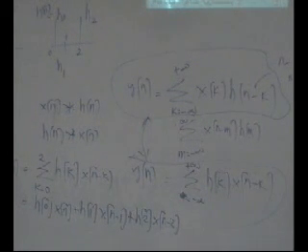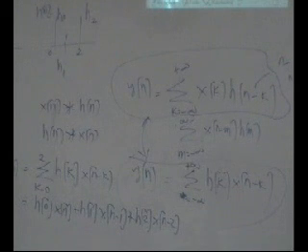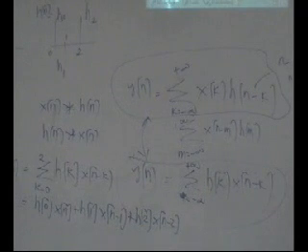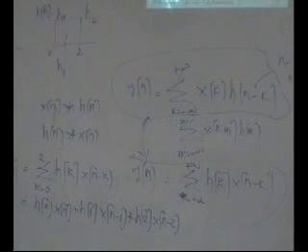So there are two ways of looking at a system, both analytically equivalent, but two different implementations. And you will keep learning about more and more implementations. There are a number of ways of implementing a system. These are just two. One is saying make copies of the impulse responses and add them together. The other is saying no, just think of it as weights.